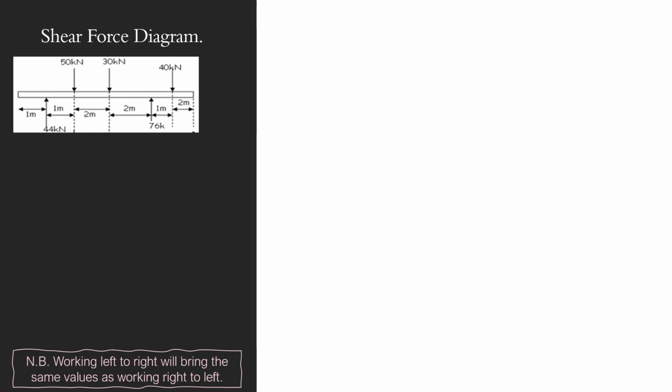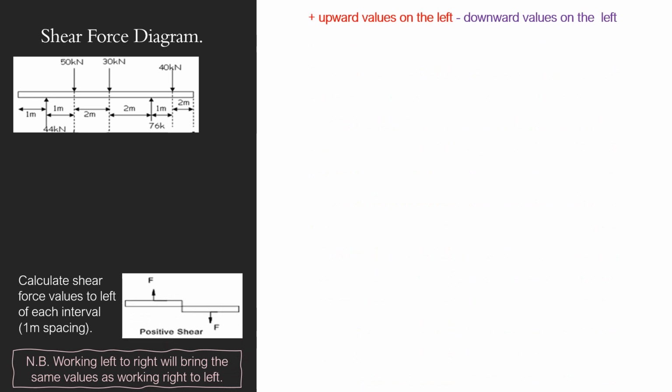Structural engineering principles, looking at the shear force diagram. First up, what I want to do is look at my beam. I'm starting from the left, and anything upwards is a positive and anything downwards is a negative. I'm using my positive shear principles, just in case you want a picture for my head.